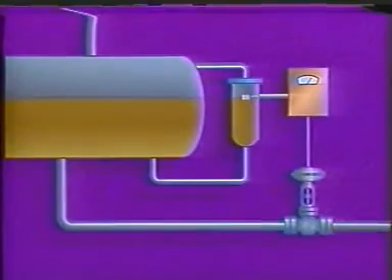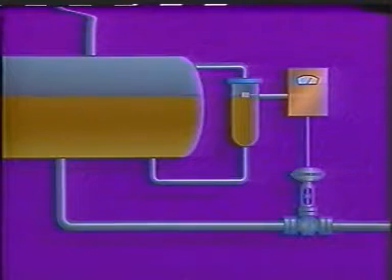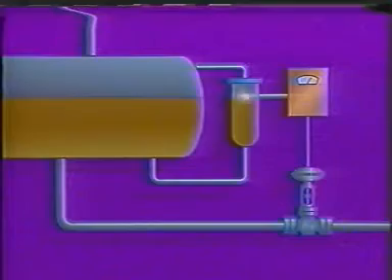This vessel provides a reservoir of fluid for a process. A minimum fluid level must be maintained or the vessel may be pumped dry. Vessel level is kept constant by measuring fluid level with a float and regulating outflow with a valve. In the four examples you just saw, keeping a process variable at a specified value or within a certain range of values was essential. And in each example, a valve regulated the flow and kept the process variable at its specified value. Regulating flow is a common way to control the variables in a process, but a valve is only one of the things we need.